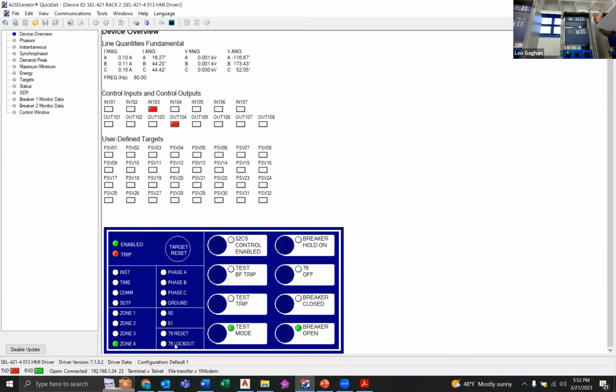And I think Paul and I were talking about the switch on default. That was a good example of a situation where we wouldn't want to reclose, where they have those safety grounds out on the line, and there's likely people in the station. So figured we'd walk through that, it will actually prevent the reclosing in that situation. So I think that's all I had. I probably ran through it faster than I intended.